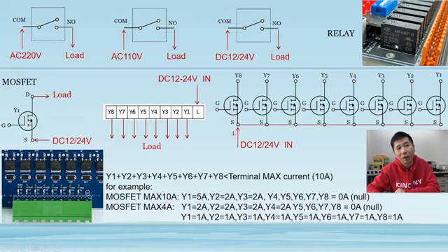You can see here, every relay shows the max ampere and max working voltage. So you can check the label printed on your relay. This first one is the relay. It is mechanical, just a physical close and open. So that will be very easy, and it can be used for AC load or DC load. But next, you can see the second, the MOSFET. The MOSFET is an electronic component that only controls DC load, and can't be used for AC load.